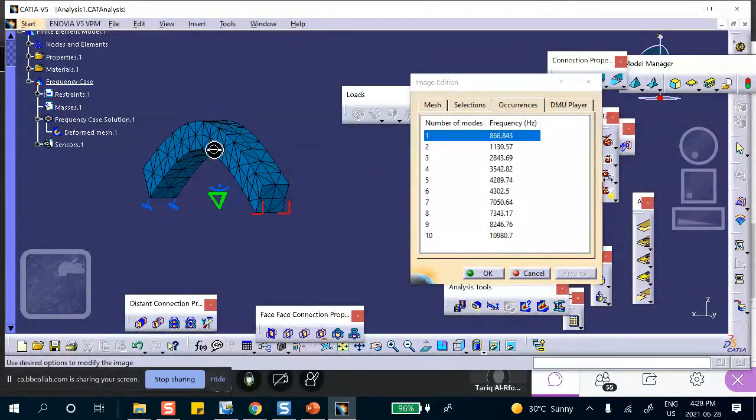Now, suppose there was a motor sitting on that I-beam in your house, a big fan or a compressor sitting on that I-beam in your basement, and that fan has a gigantic imbalance. The reason that I-beam will be resonating is that the fan runs at that speed and there is an imbalance in it.